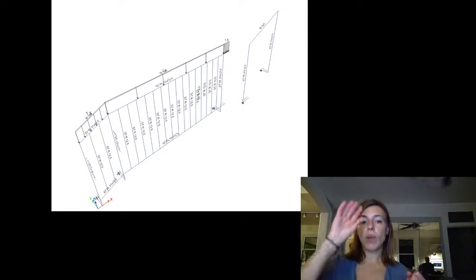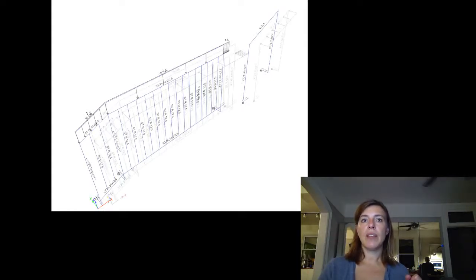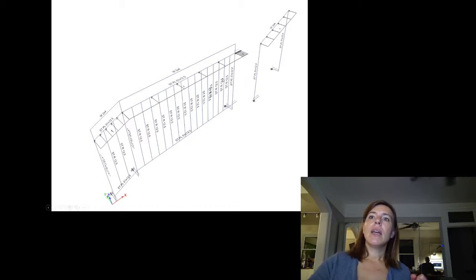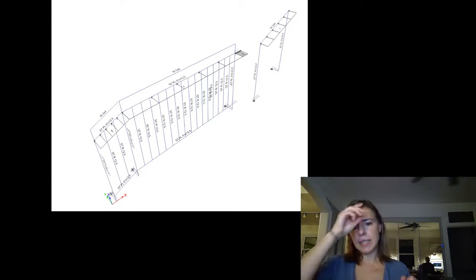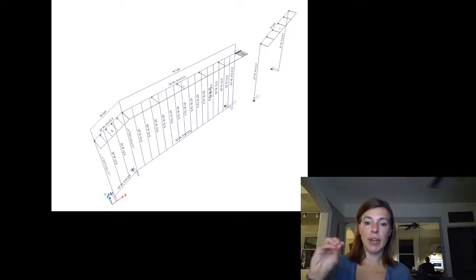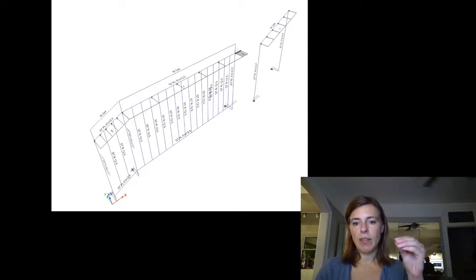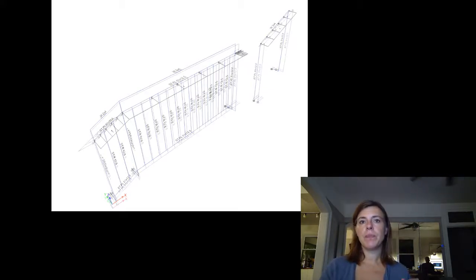So here is the 1.5 kilonewtons modeled on the layer down. Here is 1 kilonewton acting outwards. Again, it's 1 kilonewton per meter. It's only supposed to be 0.75, but that's something that is built into my model to give me freedom, where I apply it in the load combination. So I adjust my 1.5 to be 1.5 for my load combination. Remember, a factored load, live load factor is 1.5. I will multiply that 1.5 by 0.75 in my load combinations.